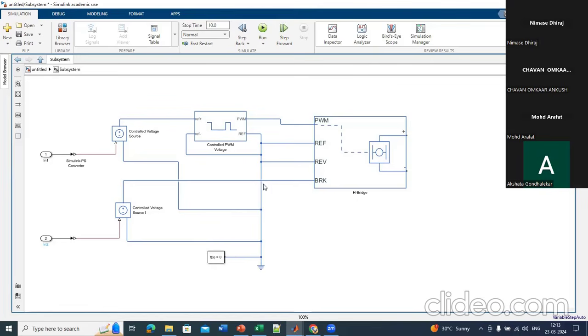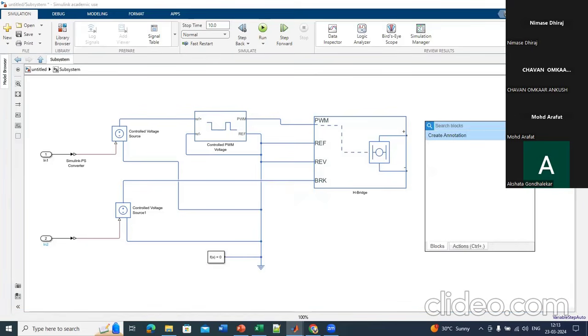Now, once I have connected these things, the next thing is to connect the current source, which will calculate the required current, and based on that current, it will draw from the battery. For that I will use a block called current sensor, from the same foundational library.